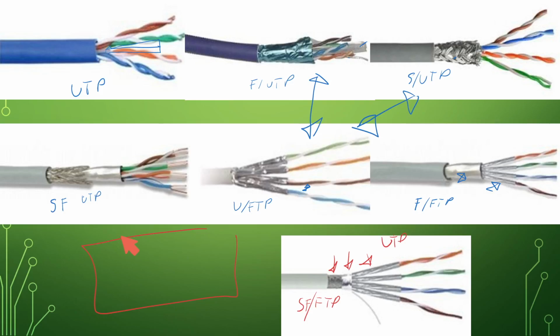If I want to run an Ethernet cable from my computer to that TV, all of these would work. Some are just a bit more overkill than others for that situation. Unshielded twisted pair would be 100% fine in this environment. But if you have to run an Ethernet cable next to a big 1,000 horsepower motor that makes an elevator go up and down, when that thing turns on and off, believe there's going to be a huge EMI spike right around that.